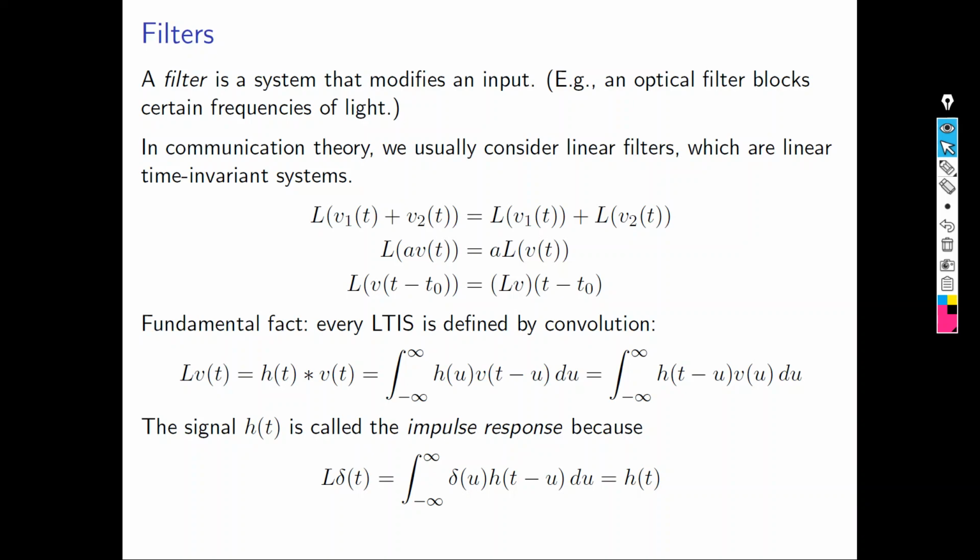To understand how it behaves, you just put in an input delta and see the response. So the output is basically the response of the system, and that's why we call it the impulse response. The response of the system to an impulse is this. So if I put in unity, a different function, what would be the output? The output will change. But basically you convolve with h(t) to find the output.